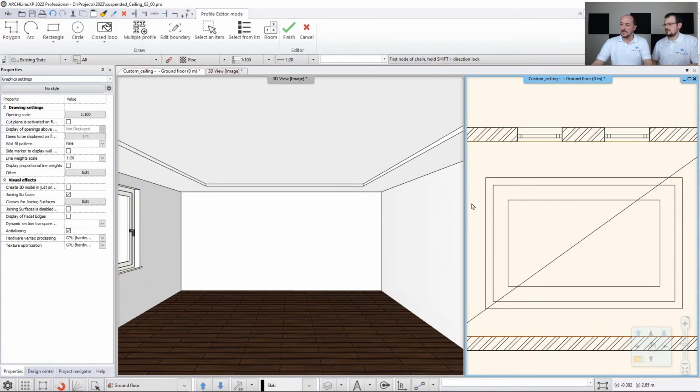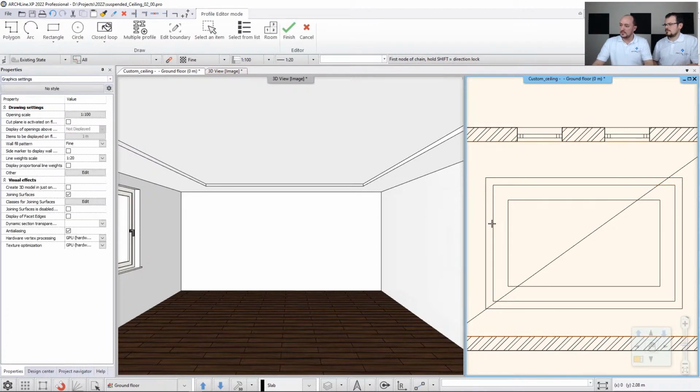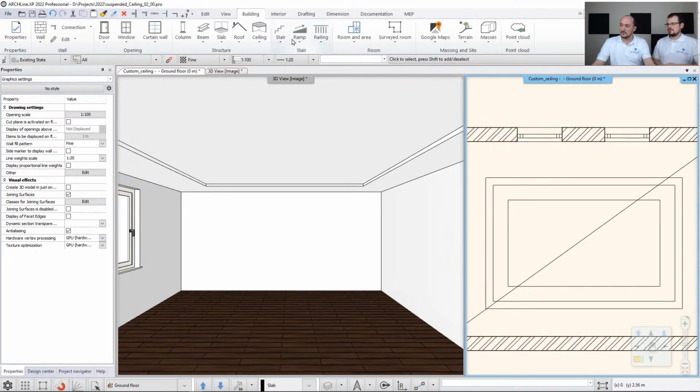So I use the create recess tool, select the ceiling, and use the outer contour of the larger shape, which is a simple rectangle. I hit enter, and it appears automatically. The default setting is 50 millimeters thick, and the size is this size, which you can see here. Now I define the second one, which seemingly won't appear in 3D, only because I have positioned two shapes, a smaller inside the large one, on exactly the same plane. So the smaller is not visible. Let me hit escape or click finish. So you need to offset one of them. Yes, I will position the large one on top of the small one.